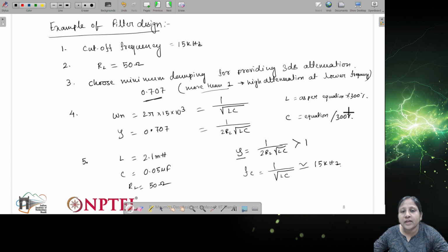That is how we adjust. Whatever values we get, the inductance will be very small, and it will be very difficult to design that kind of inductance. If we increase the inductance, it will be easier to get, because the common mode chokes available will be of higher value. So we can increase that inductance in order to wind it easily.